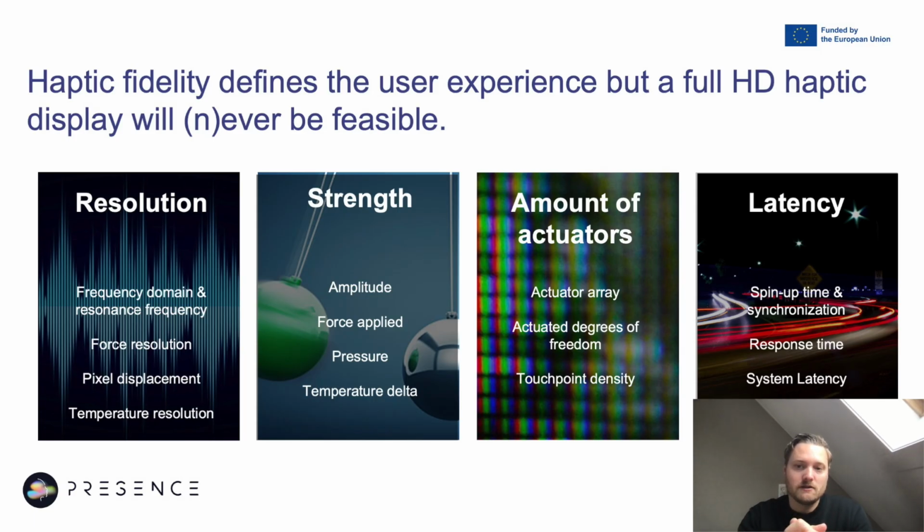And lastly, it's not really divided over the technologies, but more of a system architecture: latency. But also in actuator choice and design, it is very important to know what my spin up time is. So if I send a signal to a motor, how fast does it actually deliver the capabilities that I want from the motor, and is it able to synchronize with other systems? So can you actually make an array when you're looking at vibrotactile feedback? And then also, what's the response time in such a synchronization? And obviously you also have a system in place that has system latency. What's the latency from your microcontroller to your actual motor? What's the system latency from your physics engine inside your headset or inside your computer environment to the microcontroller? What is the process time of the microcontroller? Everything like that you need to take into account in order to determine the latency of a system.